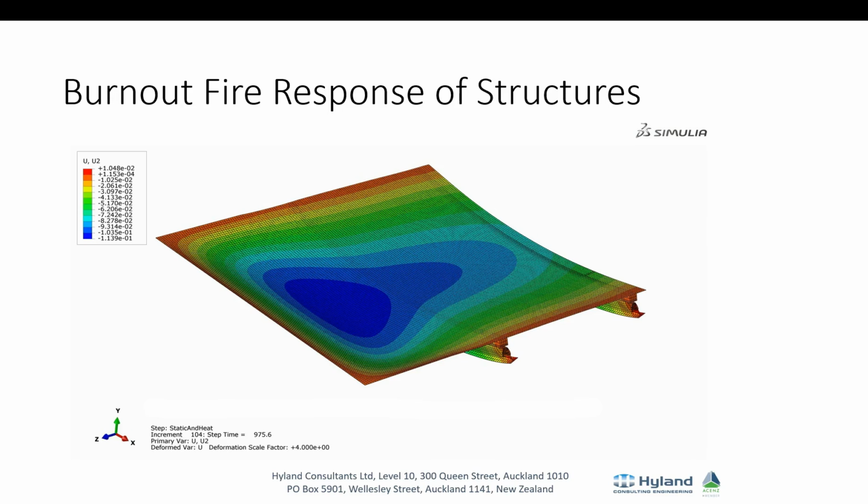So we've used Abaqus to analyse what's happening in terms of deformations of slabs under fires using gas time temperature curves that we've had from fire engineers. We then apply that into the Abaqus using heat transfer analysis functions, and then do deformation analysis following on from that using the temperatures that have been derived.